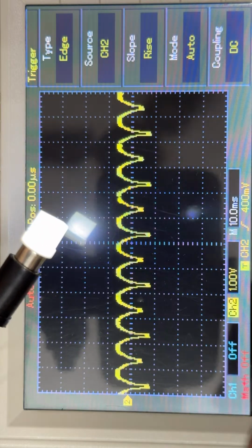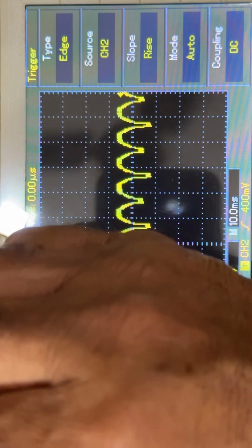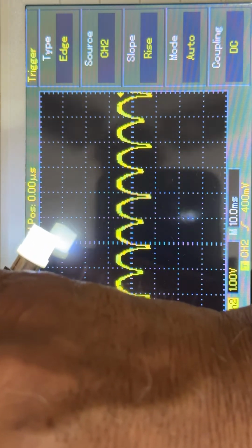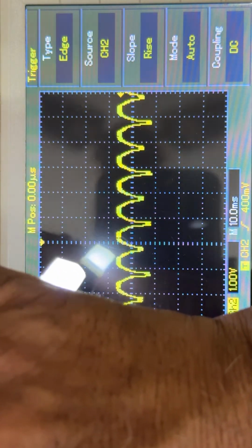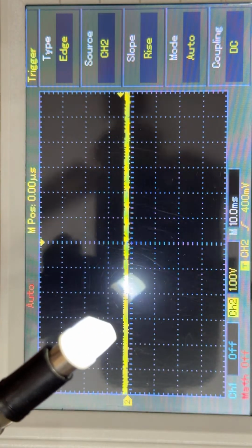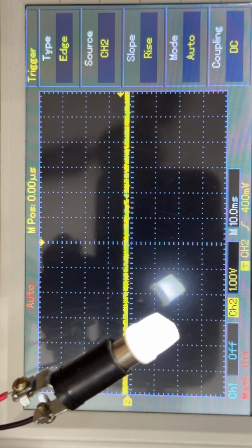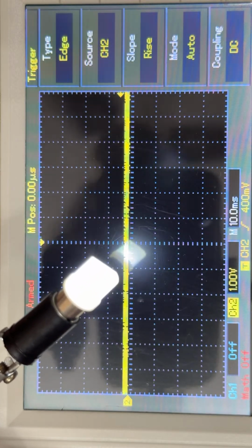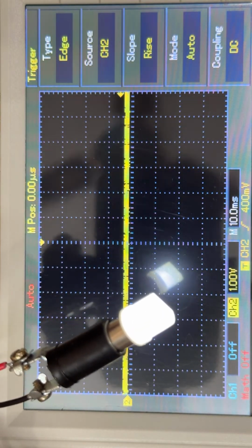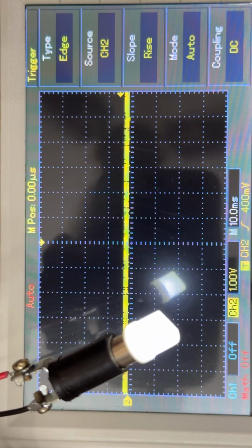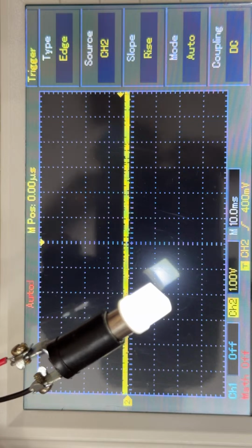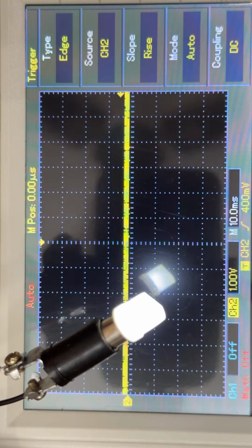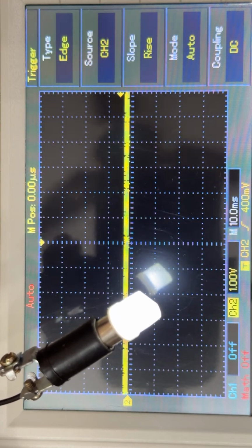And when I connect the capacitor again, you will observe this flickering will be changed. I hope so. You have to confirm to me. This flickering will change because why does the light flicker? Because of the pulsating DC, this LED flickers.